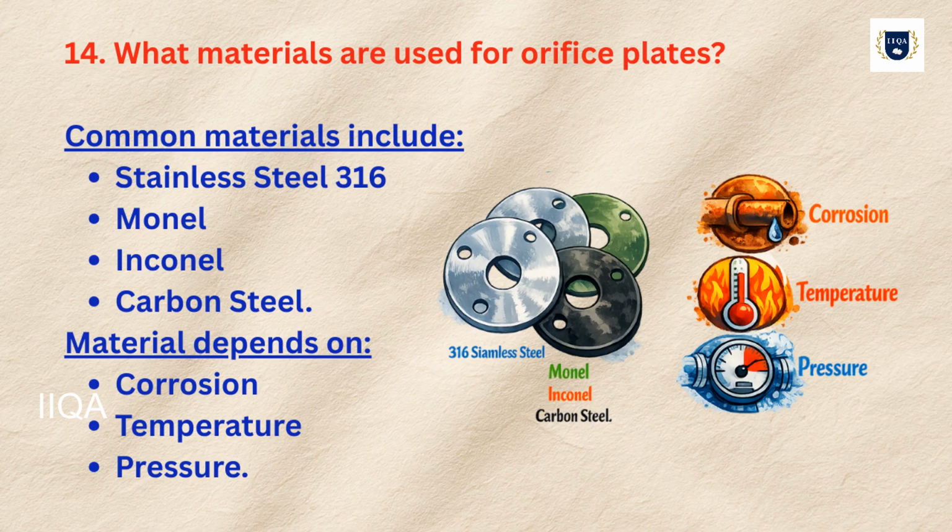What materials are used for orifice plates? Common materials include stainless steel 316, monel, inconel, carbon steel. Material depends on corrosion, temperature, pressure.